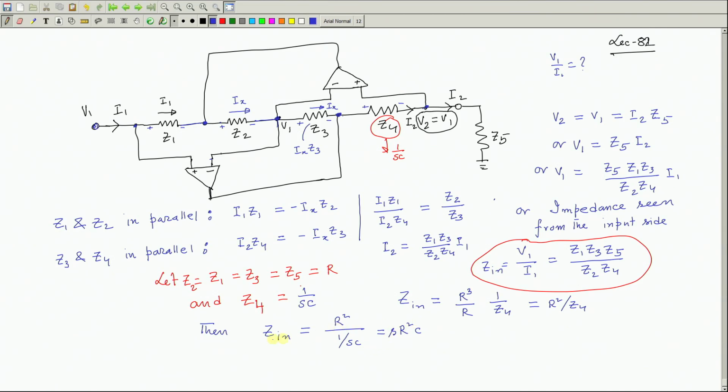Now, the impedance seen from the supply is S times L equivalent, because for inductance only the impedance seen is SL, and for capacitance, 1 over omega C. Similarly, if Z4 is an inductor, this reciprocal business will make it a capacitance, and so on.